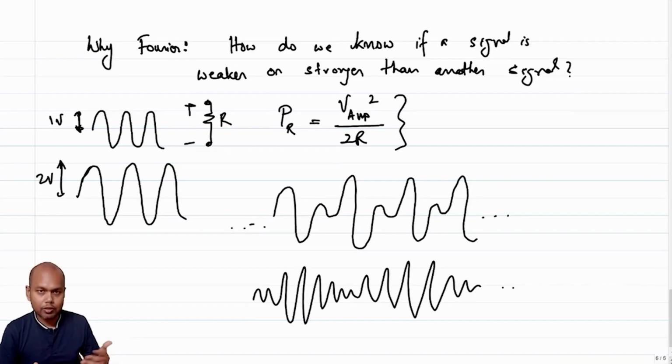If you remember, we talked in the first lecture about the significant need of filtering in RF analysis and RF design. When we say filtering, we essentially mean that we would like to pass signals of certain frequencies and not pass signals of other frequencies. So in order to understand which frequencies to filter out, we need to first understand what frequency components exist. And if we want to know that, we need to know how to do Fourier analysis. That's one of the motivations of why we need to do Fourier analysis. Given that the motivation is clear,